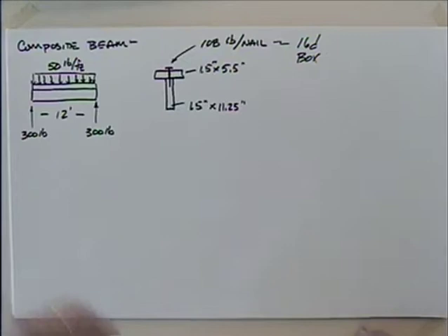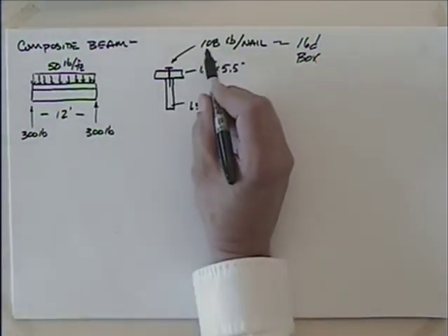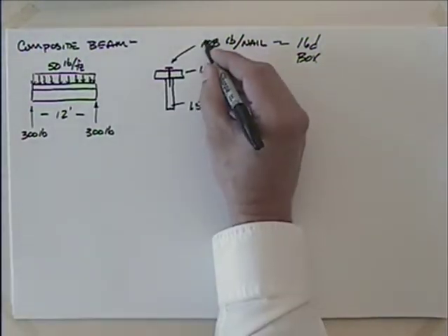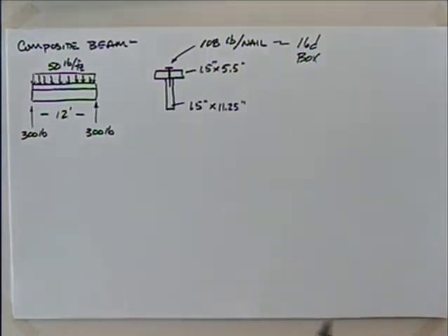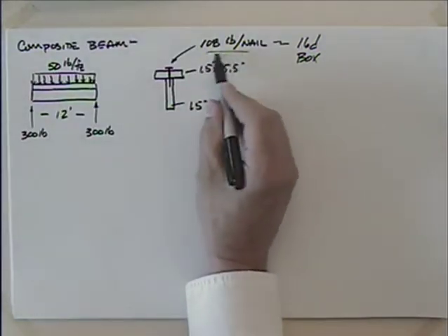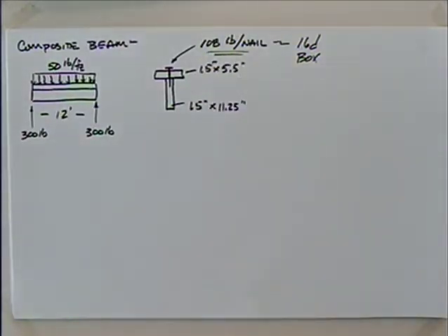So you might say, well, gee, I've driven a nail in the wall, a 16 penny nail, and I bet it would hold more than that. I mean, I'm around 200 pounds, and I could maybe grab that and hang from it. Well, remember, this probably has quite a bit of safety factor in it. What if it goes into a bad spot in the wood, it misses something, it cracks the wood slightly? So usually we've got some pretty heavy safety factors in that number.